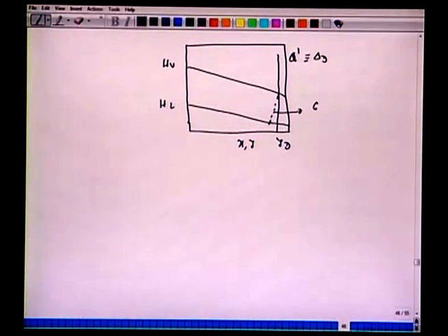This is X0 and here we have HD, and this is HL0 corresponding to XL0. This is the mole fraction of the liquid going back to the distillation column, and when we connect with this, we have the first operating line corresponding to this XL0.